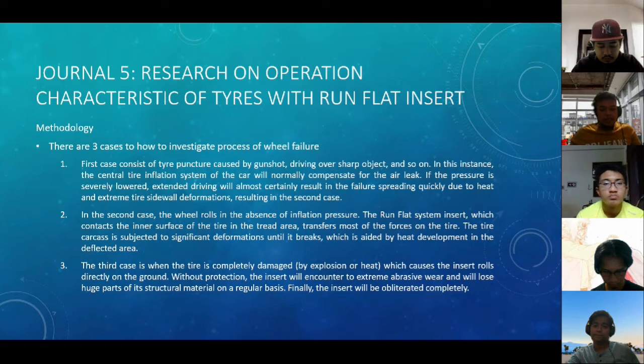The third case is when the tyre is completely damaged by explosion or heat, which causes the insert to roll directly on the ground. Without protection, the insert will encounter extreme abrasive wear and will lose huge parts of its material on a regular basis. Finally, the insert will be obliterated completely.